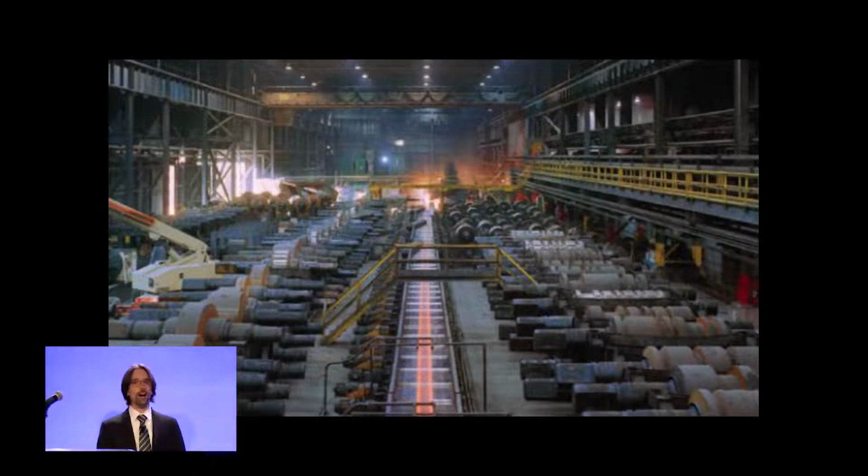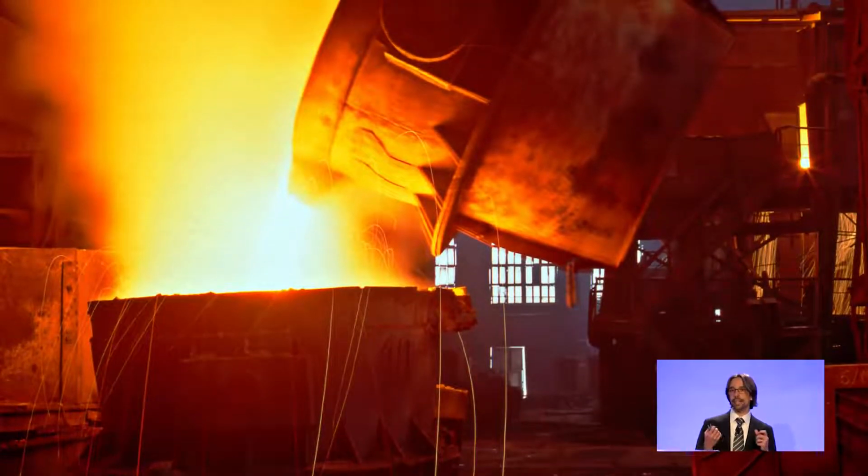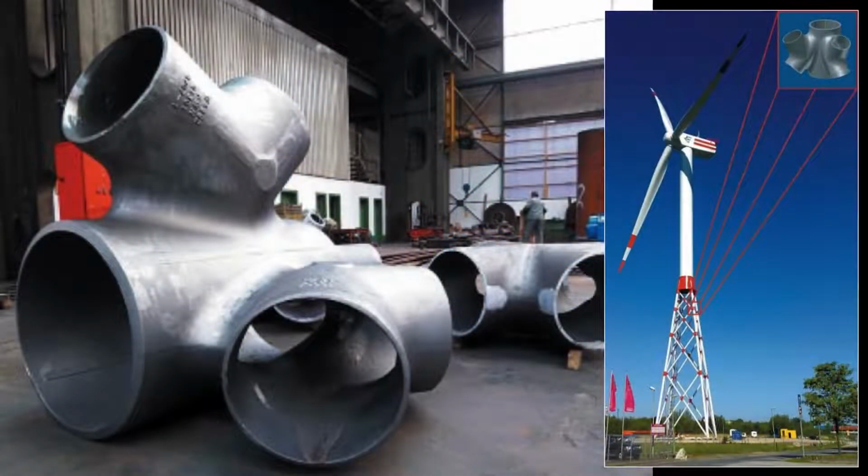So what you see here is a hot rolling manufacture of an I-beam, or what we would call a W shape. A lot of people don't realize, though, that all steel is actually cast. So at the top of that image, you'll see that's a continuous casting process where molten metal is being poured continuously and is cooling and solidifying. And as it's still red hot, it's being rolled into the I shape that we're used to seeing. But with steel castings, what we do is we pour that molten metal into a complex shaped mold. And the steel actually freezes in that mold and takes the shape of that mold. And that's really exciting because we could make monolithic structural steel elements that have any shape imaginable.